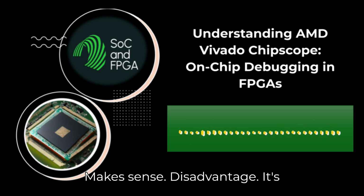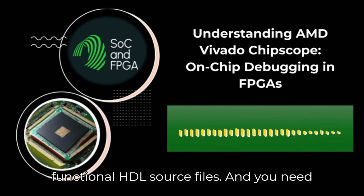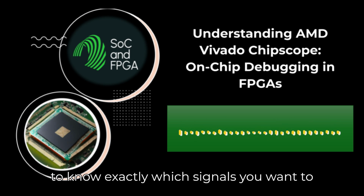Makes sense. Disadvantage? It's intrusive. You have to modify your functional HDL source files, and you need to know exactly which signals you want to probe right from the start.